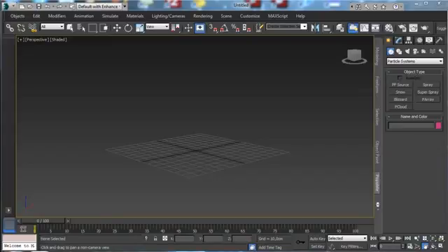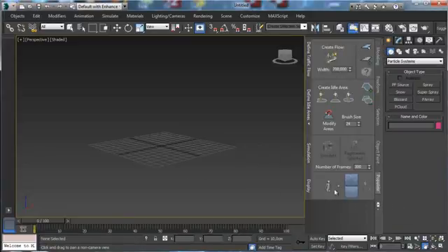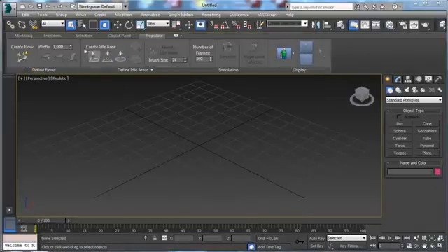Something that can be done really simply is using the Populate menu there over the ribbon tool, and you see that there we have all the commands. The first thing we have to do is to create the flow. The flow is the flow of people walking. So we have to press create flow, and then we have the possibility to create the flow over the viewport.